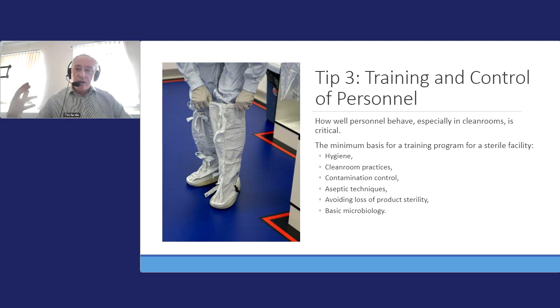So with hygiene, that's not only a discussion around personal hygiene, but also the frequency of glove disinfection when the person's in the clean room, and hand washing going through the changing process. And then going into the clean room, this idea of slow, deliberate movements, and showing the difference between walking quickly and the number of particles that are generated, and walking slowly.